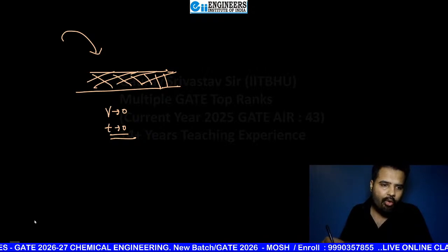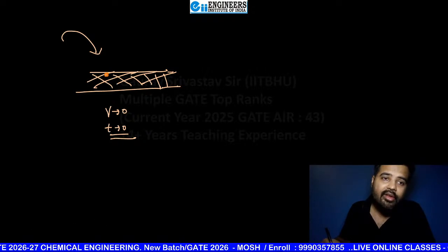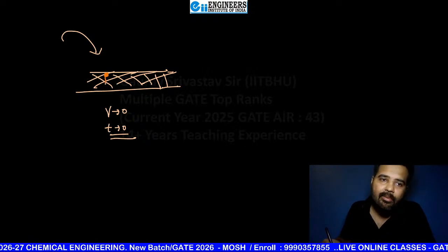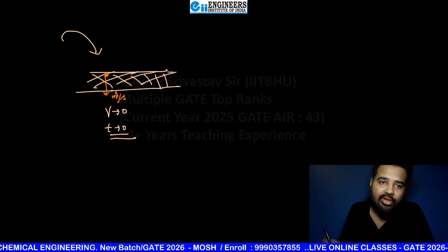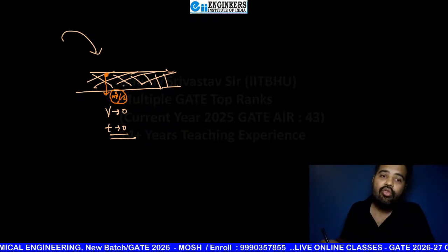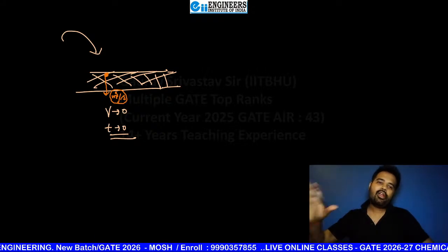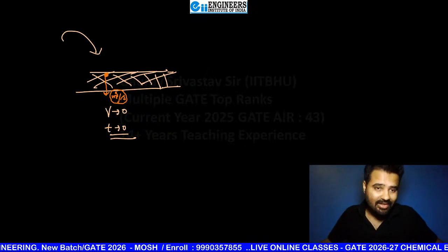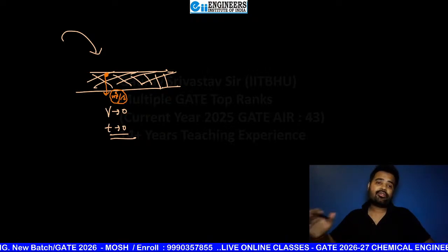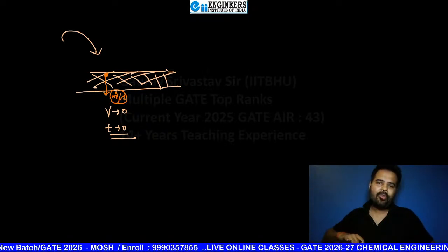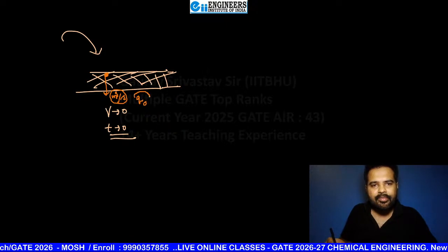So the first drop out of your slurry, only the filtrate can enter here. The filtrate that enters here will exit from here, and that will provide you initial drop. So this is the initial flow rate. In order to get any mathematical expression, you deal in this manner. Not only in this subject, you will also find it in other subjects like mass transfer rate, heat transfer rate, and many more things. So this is your initial volumetric flow rate.